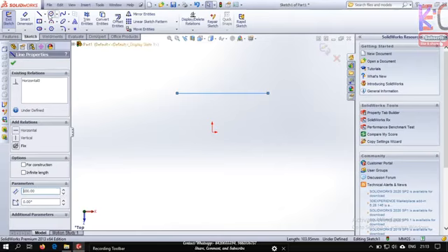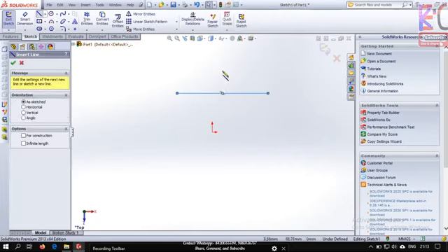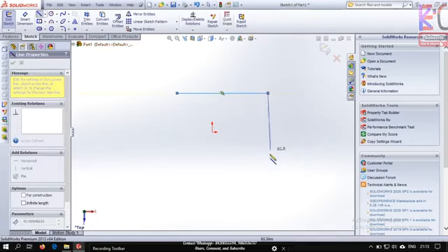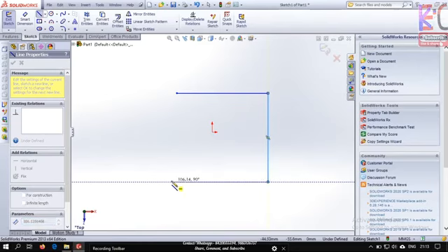Fine. Next, again I can click over here, then I can draw again. I can go over here. Now I could continue without pressing ESC. If I don't press ESC, the line will continue. Okay, I could go over here. Now your interest is to draw over here. So what you can do, you could bring this line over here. Don't click it. Mandatory, you don't click.